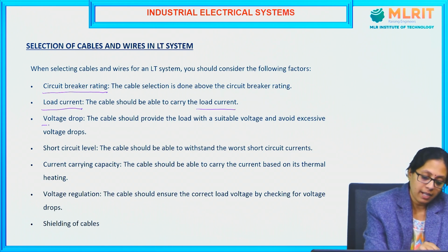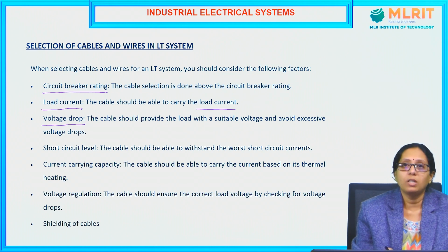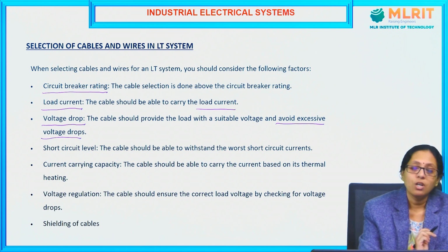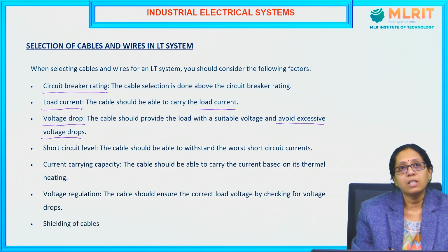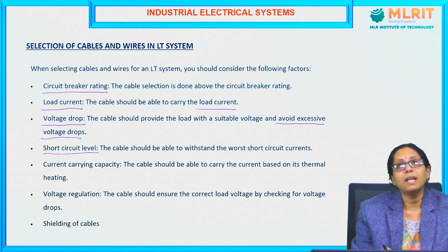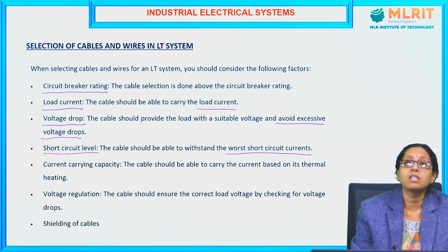Third criterion is voltage drop. The cable should provide the load with a suitable voltage in order to avoid excessive voltage drops. Next one is short circuit level. The cable should be able to withstand the worst short circuit currents also.